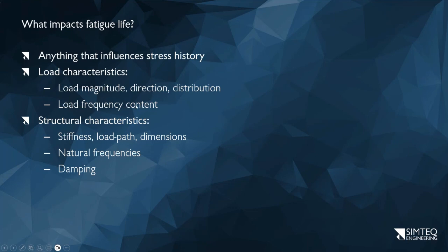Based on whatever the load does, it determines whether or not I have to compensate for that effect. In other words, whether I can do an equivalent static calculation or whether I have to do some kind of transient calculation. The same goes for damping in the structure, which also plays a role. If we operate close to a mode, the response tends to be dramatically more, which means the actual response is critically determined by the amount of damping and the distribution of damping.